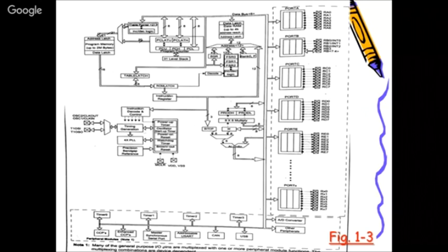This may not be very clear to you, but I'll just try to tell a few things, then we'll move forward, because later there are better, independent figures. So here mainly you can see there are ports from port A to port G. Unlike your 8051, where they don't say port 1, 2, 3, here port A starts, and alphabetically they call it port A, B, C, D, E, F like that. So there are 8 ports in the highest family, and then unlike your 8051, it's not that all the ports are symmetrical, that all have 8 bits.